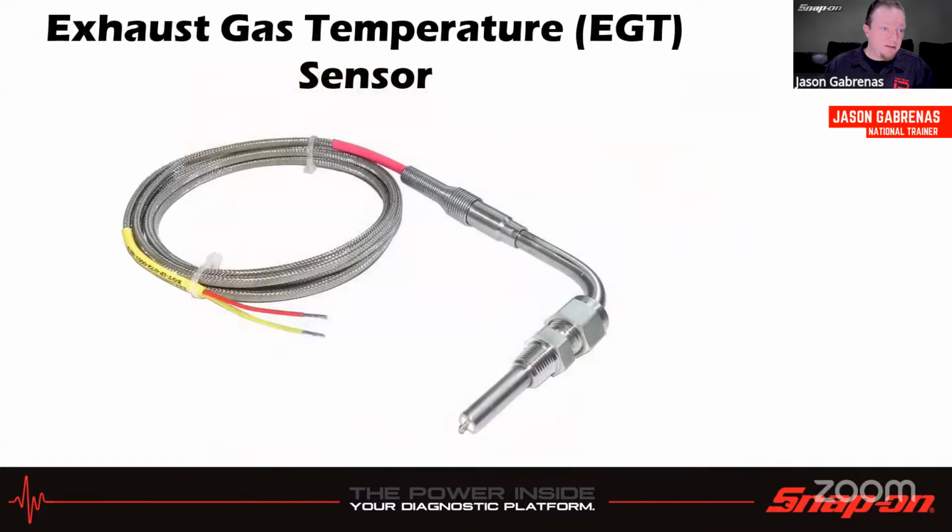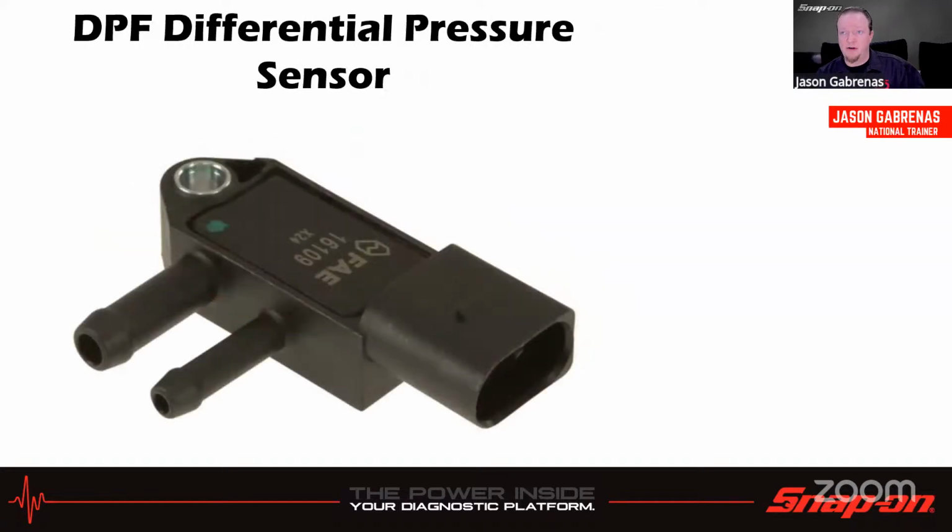Then, to go along with that, we're going to use the exhaust gas temperature sensor to monitor the regen process. What's the temperature going in? What's the temperature going out? So it's going to measure multiple points along the way, see what the temperature in is and what the temperature out is, and know whether or not the regen's actually being carried out and working when it needs to. Sometimes those need to be relearned.